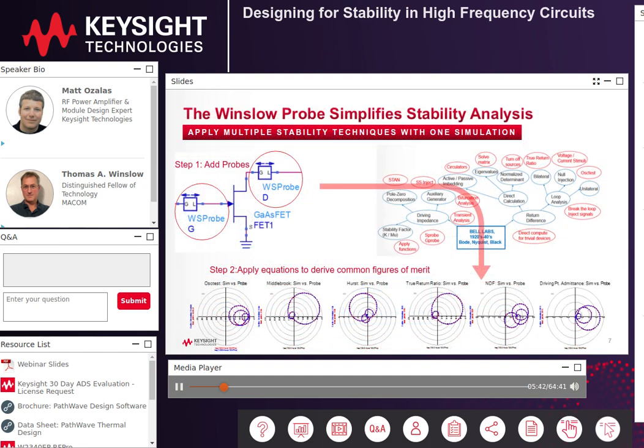Okay, well, at the risk of giving away the ending, I want to tell you what all this is building to, which is the concept of a general stability probe in the simulation tool. This probe can allow you to apply just about any type of stability analysis technique to your circuit in a very straightforward manner. And the probe is nicknamed the Winslow probe because it was developed by my co-presenter today, Tom Winslow from MACOM. Tom had been struggling with designing these high-frequency circuits for a long time, and he was looking for a simpler approach, so he developed this probe. And he worked with Keysight to get it into our tools.